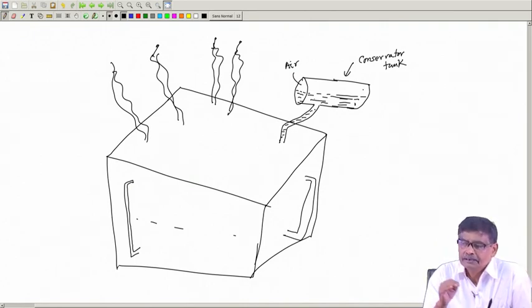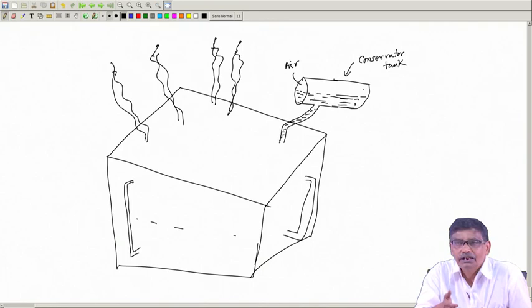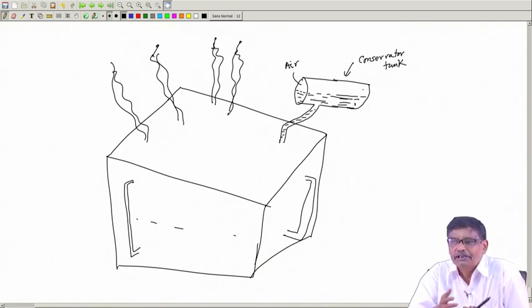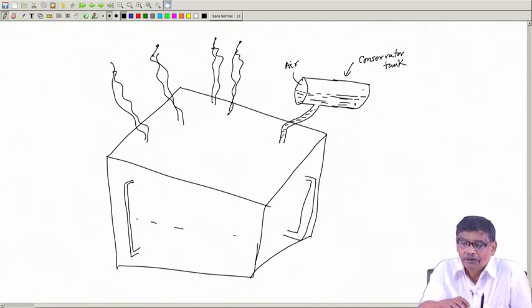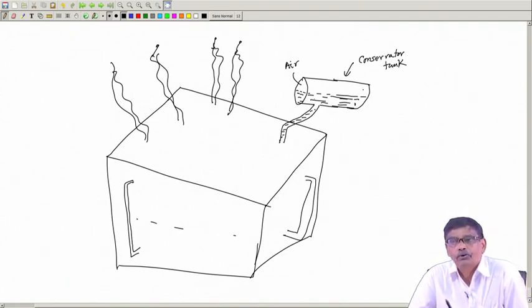Now, you imagine that you have connected load on the transformer. Only core loss was taking place when the transformer was under no load condition. Now, through the secondaries you have connected, it is delivering full load, full kVA. In that case, copper loss comes in. So, more heat will be generated and temperature will rise.